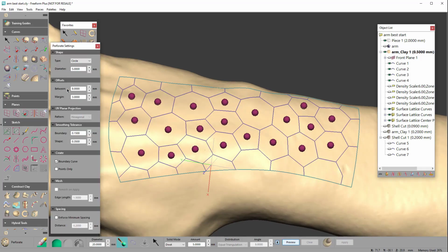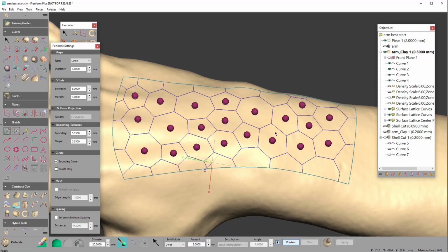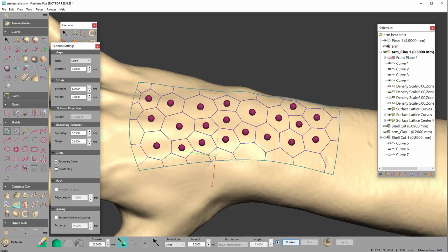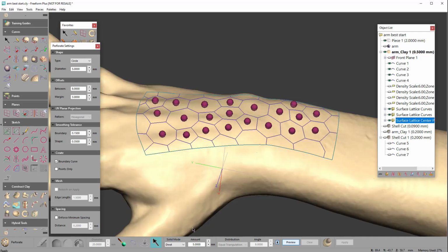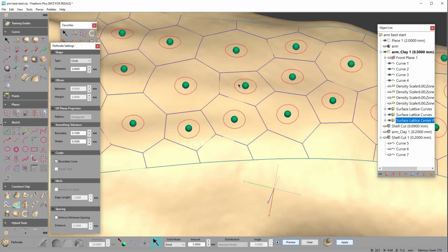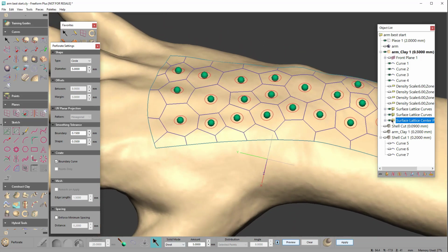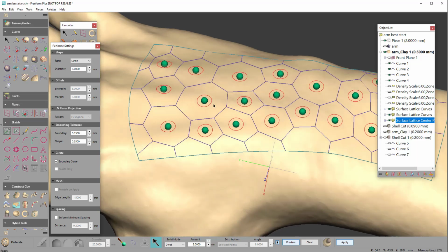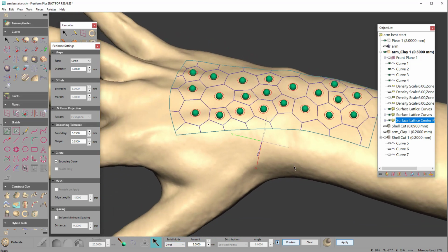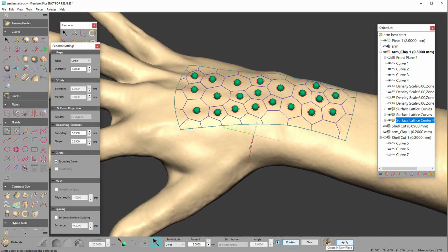So if I come over to here, we can select those same center points and utilize those for my perforation settings. So if I hit this select here and then come over to center points, we can utilize those to preview. So you see here, when I hit select here and then click on this and say select all, it goes ahead and places those divots right at the points here. So we can go ahead and just hit apply. Obviously, I don't want to cut holes into this, but just to show you how this interoperates with it, so we can cut holes in and then use the rest of the boundary for other things.